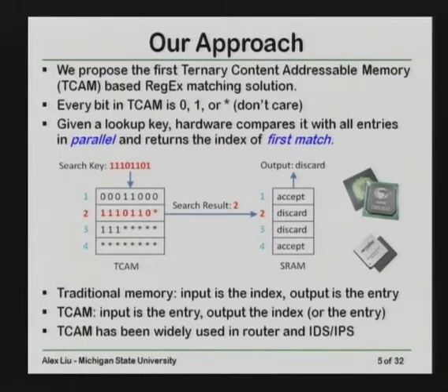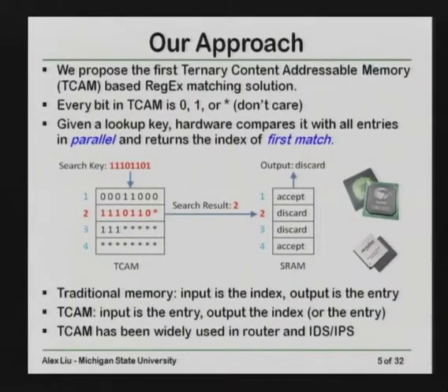in SRAM. So every TCAM chip itself has TCAM circuits, and also has associated SRAM circuits. The TCAM is used to store the rules, and the SRAM is used to store the decisions. And there's a one-to-one mapping between the TCAM entries and SRAM entries. Compared with traditional memory, the lookup process is kind of reversed.